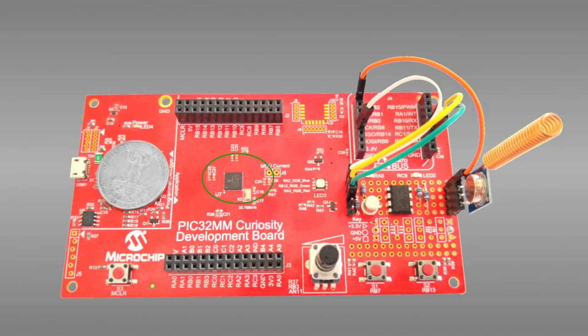The microcontroller we're using here is from Microchip and is based on a MIPS 32-bit processor core. MIPS processors are often used in home internet routers, but this one here runs at only 8 MHz. It has 8 kilobytes of RAM and 64 kilobytes of flash ROM. Kilobytes, not gigabytes. Any standard smartphone these days probably has 2 gigabytes of RAM, 64 gigabytes of flash ROM, and runs at peak clocks of up to 2 gigahertz. But our little key fob is supposed to be powered by a coin battery like a CR2032.